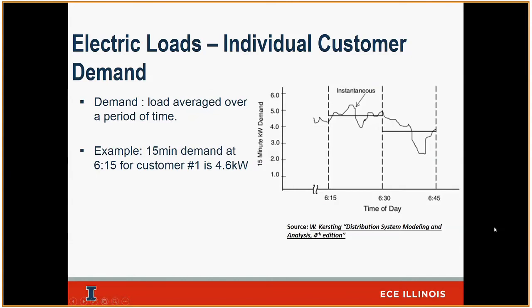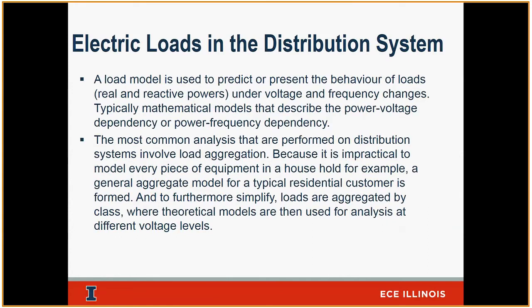Typically, on the distribution side, I don't control a lot of what happens on the transmission side. So I get a particular voltage that comes from transmission, right? I'm connected to a transmission bus, and I'm bound by its voltage and its frequency that is fed to me. So as that voltage and frequency change, I need to better understand how that impacts my circuits downstream. Is the voltage going to dip if I have a big dip in voltage, or if the voltage rises, how are my loads going to react?